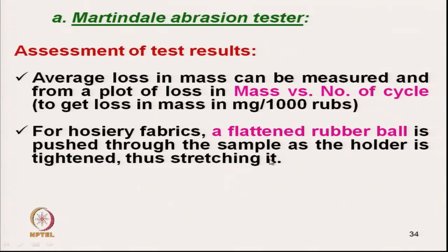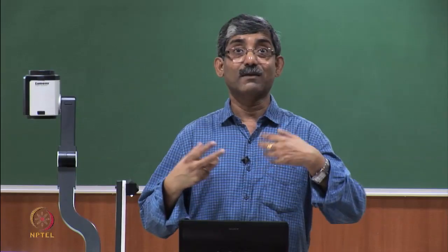And for hosiery fabric, due to the extensibility and to make it the severity of the test, because the hosiery fabric is a knitted fabric, there will be relative movement of the yarns. So, that is why the fabric will show the higher abrasion cycle.